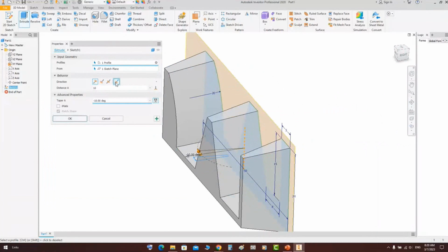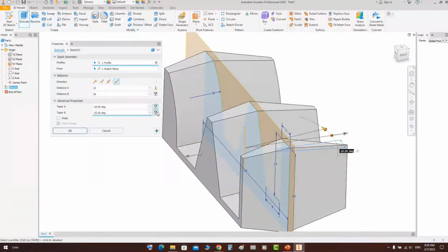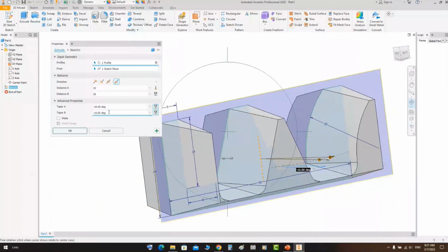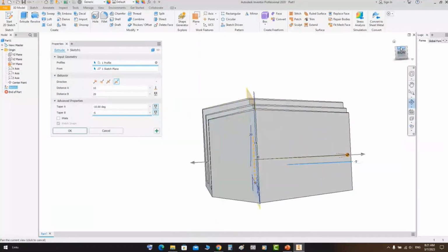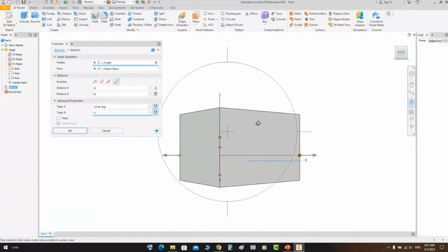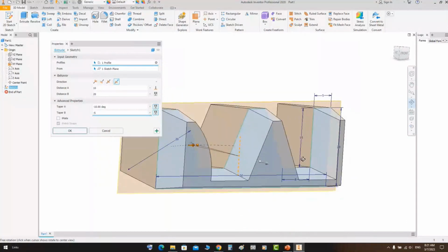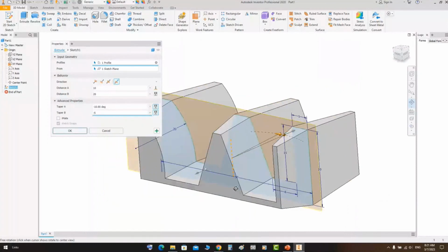Okay, let's make it asymmetric to get two different values. So here you will find an option to make a taper from the two sides. Let's make it 5 degrees only. Okay, like that. So you can make a taper for the positive direction and for the negative direction, and you already have two different distances like that. I think those are very good options for the extrude and will help you in many different things.